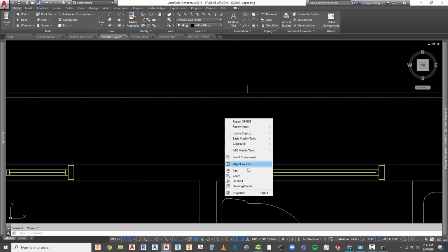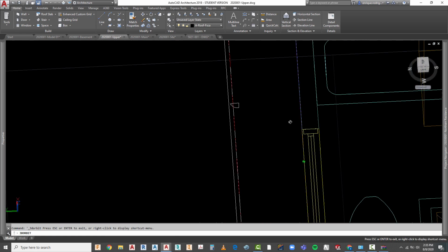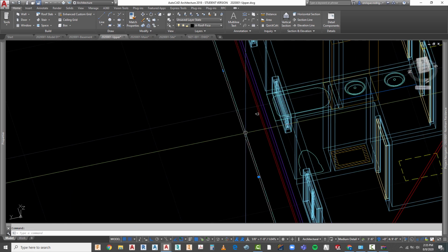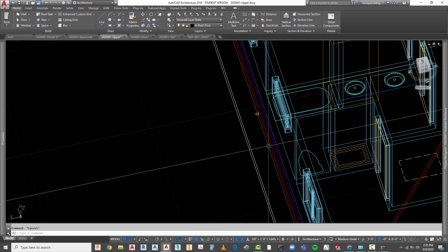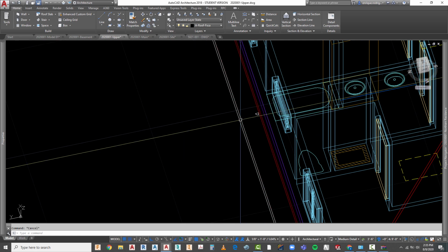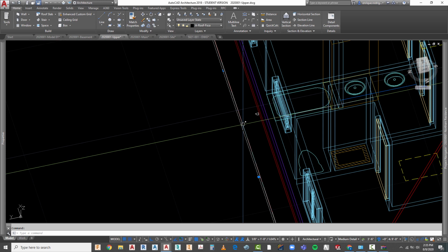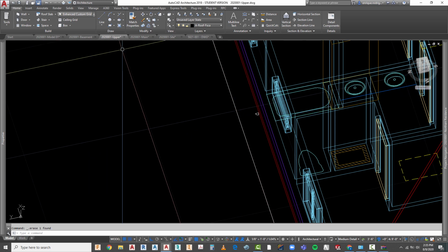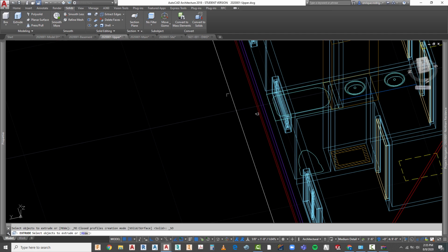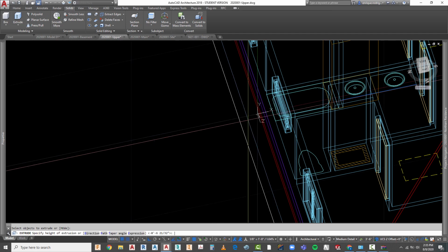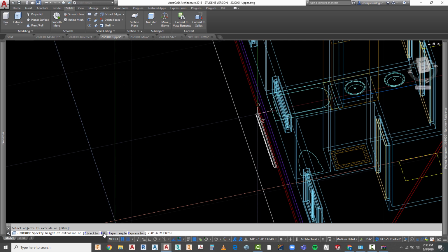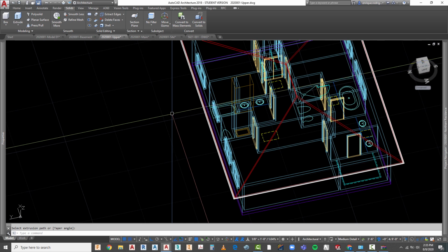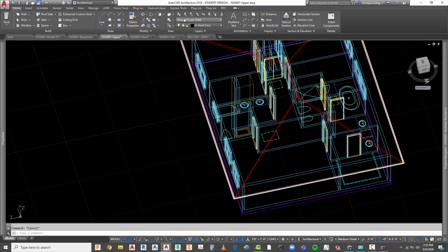So actually what I've done right now is I've created an offset mark for this guy. Granted, it is not in the right location, but let's see if that works. So make sure that this is the path you choose, not the inside one. I'm going to delete the inside one so we don't get tempted. Solids, extrude, select the object, and once again I'm going to go path. I'm going to select the path here. Let's go to top view and see if that solved our problem.